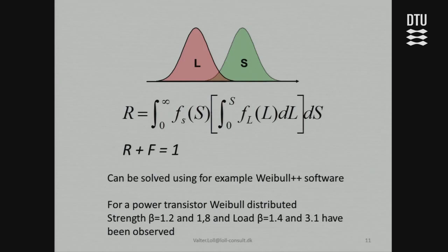And Carter also was looking into that using his safety margin and his loading roughness. If we plot the safety margin against the logarithm of the failure rate, we can see that we have 3 areas. Here the failure rate is too high. It's not a useful design. Here it's too sensitive, not a useful design.